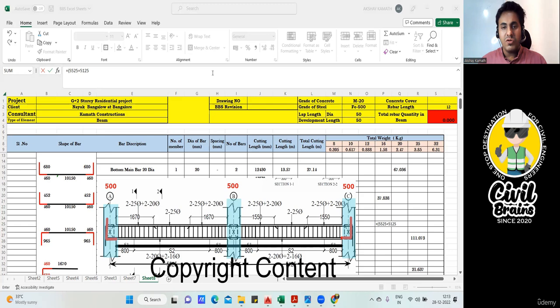If I remove half of the column from here, and half of the column from here, and deduct this from the length I got, will I not get the clear span distance? Obviously, I'm going to get it, from the inner of the column to the inner of the column. Right now I was getting center to center, but the entire column is 500, so only this length has gone here. So this will be 250, half of that.